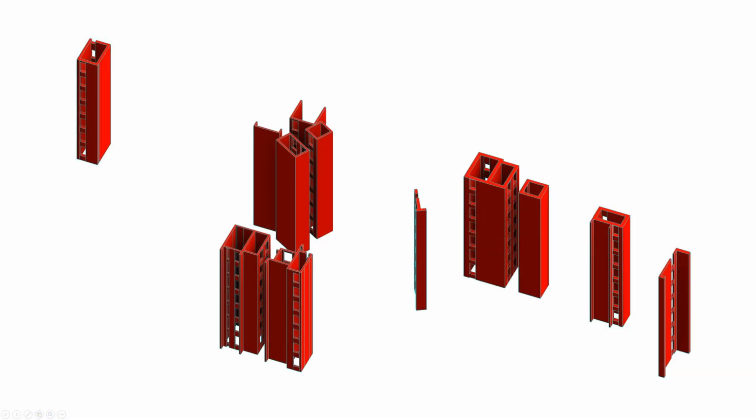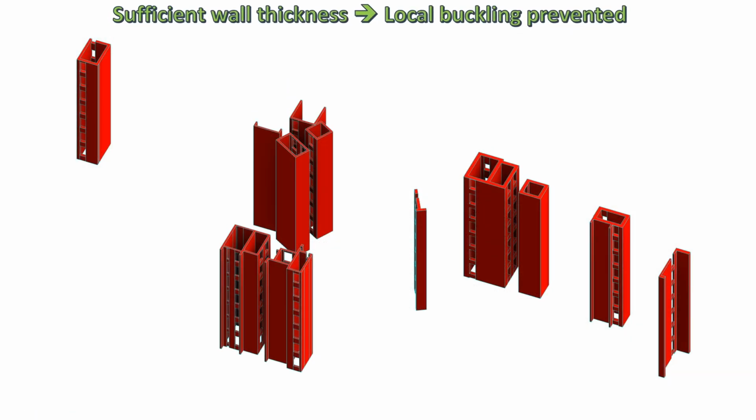By providing sufficient thickness of shell element, the buckling strength of the concrete wall is equal to or higher than the stress obtained from structural analysis. This is a guarantee that there will be no local buckling for all shell elements, hence, the structural engineers could allow the structural analysis software to proceed with the concrete wall design on shell element without the need to consider